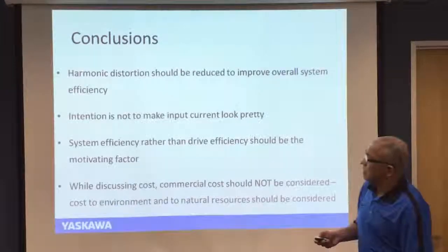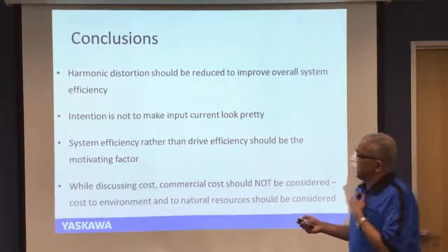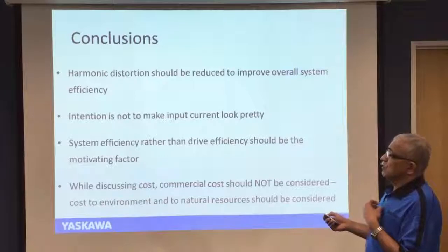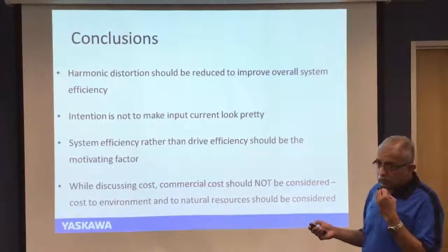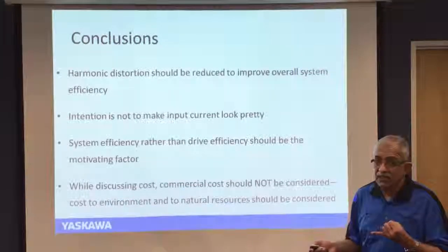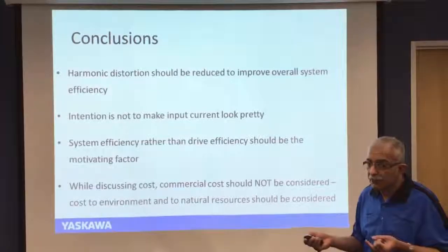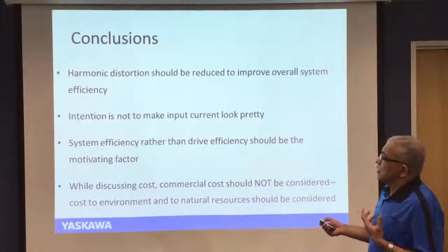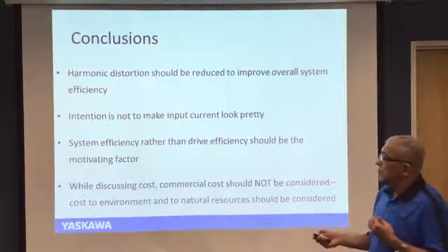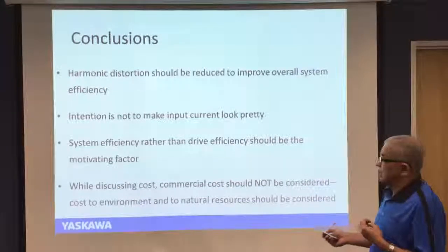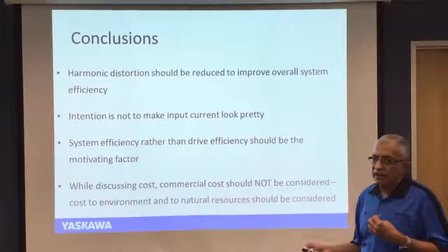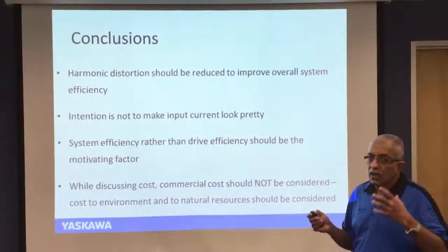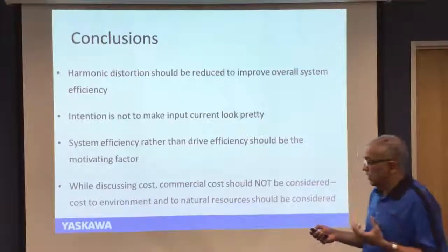So in conclusion, what I have discussed today is that it is important to reduce harmonic distortion, from an efficiency as well as from a power factor or VAR point of view. It's important that we should consider this. And the intention is not to make the current look pretty. The intention is basically to improve system efficiency. And that should be the main motivating factor, and to reduce the VARs necessary in the system.